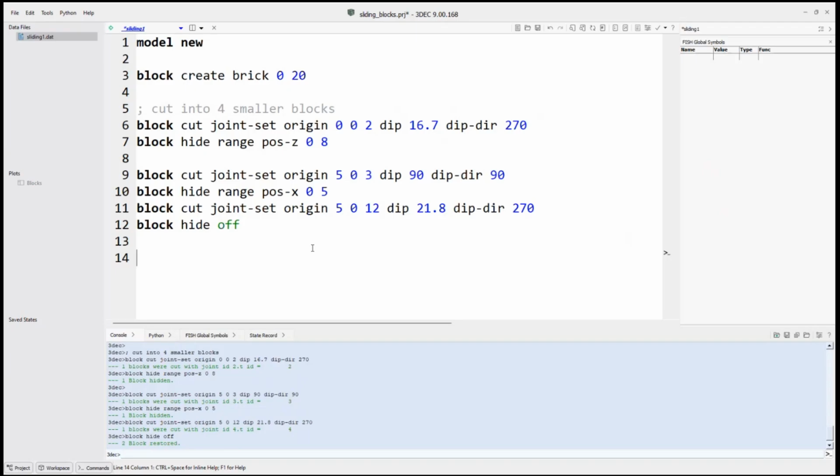It is also possible to run the blocks perfectly rigid. That means the blocks themselves don't deform. They're infinitely stiff. We don't need to give them a modulus. The thing with using rigid blocks is that we can only fix the entire block. You can't just fix one boundary like you can in continuum models. In a continuum model, you usually put roller boundaries on the side or fix the bottom, something like that. That doesn't really make sense when the blocks are rigid. You either fix the whole block or you don't.